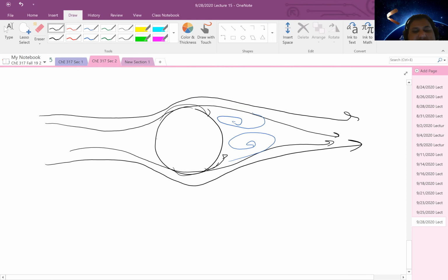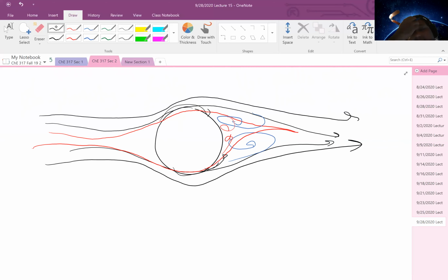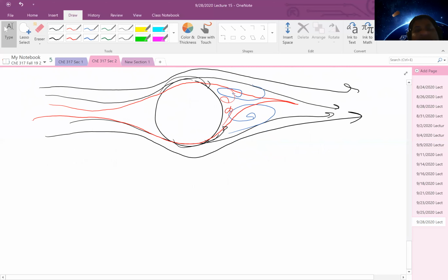And it's particular to an object of interest at what Reynolds number this boundary layer thinning happens. What it means is at high enough Reynolds number, this area of the vortex formation is greatly reduced. And that results in less drag on a system.